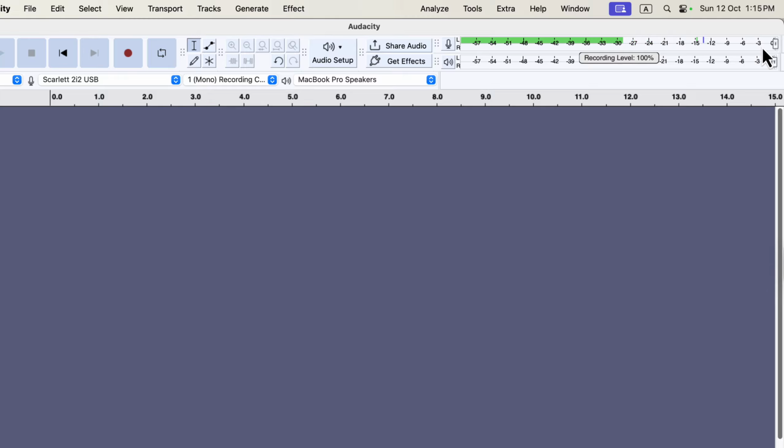If your audio gets into the red region, there is a chance of distortion or clipping. Notice the maximum level on this meter is 0. If your level is more than 0 dB, you cannot see it, but your audio will be clipped or distorted. The most important factor here is your distance from the microphone.